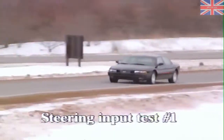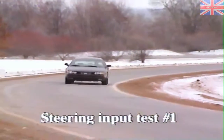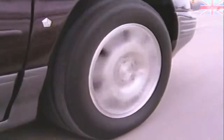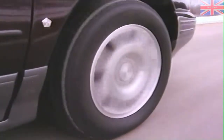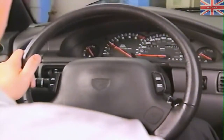By taking sweeping turns at the vibration speed, we can determine if the wheel bearings and suspension components contribute to the vibration. The problem remains consistent throughout the turns. The wheel bearings and hubs are apparently not contributing to the vibration. After returning to the service bay, the neutral run-up test further confirms that the trouble is related to vehicle speed and not engine speed. Let's review our results so far.